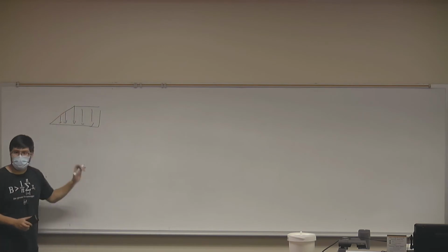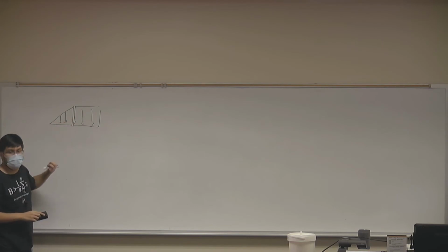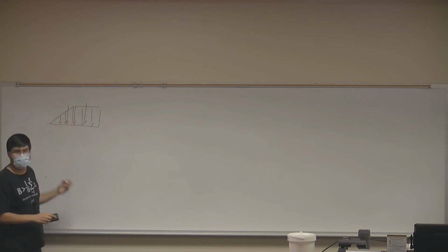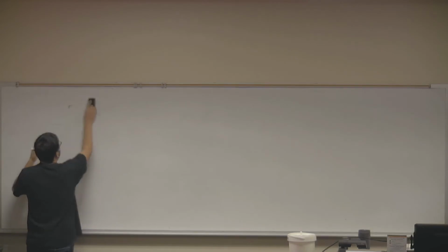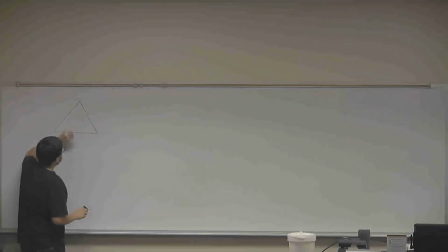Instead of trying to find one force and the location, it's okay to break this down into two segments, a rectangle and a triangle, each with its own force, each in its own location. So if I were to have a triangle that's not equilateral, it's probably better to break it down into two triangles, each with its own force and each at 2/3 from the small side. Okay? So, good question. I'm glad you brought it up. Let me go ahead and look for a problem that has something like that, because that'd be a good exercise for us.